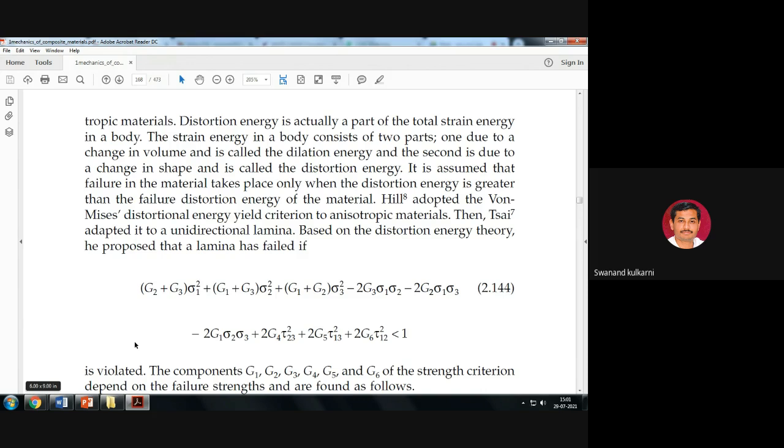You know that in your second year you have studied the chapter related to strain energy, and in that we have seen how the energy possessed by any body is calculated, because whenever changes happen, work is done, and there are various forms of work. One kind of work is that wherever force is applied and displacement happens, deformation happens in the material. So the force applied into the deformation happening inside the material, this product gives the energy possessed by that body.